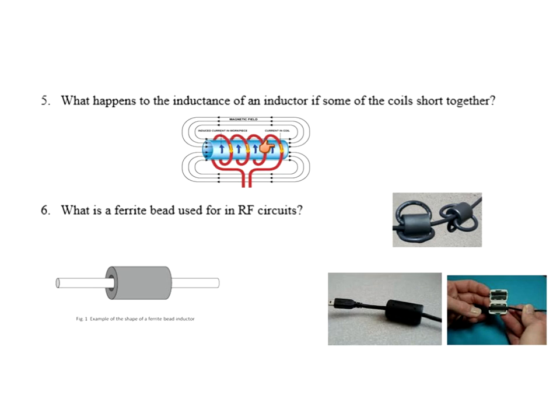Now here's an interesting thing about inductors. In electronics, you don't have to have turns of wire to create inductance. Sometimes what you'll have is just what we call a ferrite or ceramic bead on the wire. Here's a picture of one. You've probably seen these on mice, these ferrite beads. They're encased in plastic. If you open it up, you can see the ferrite bead in there. But here's another one here too with many loops of turns in the ferrite bead.